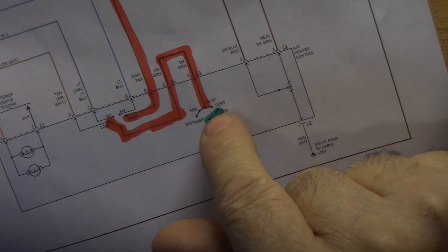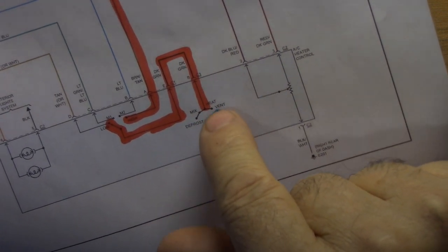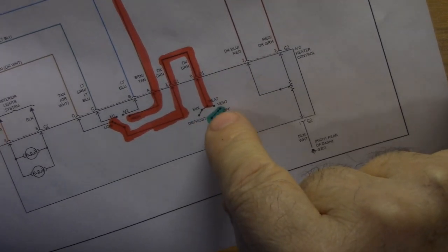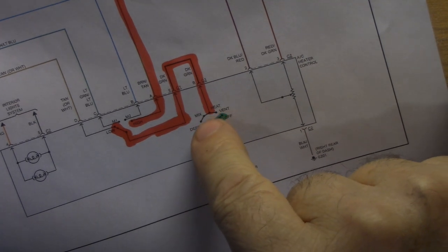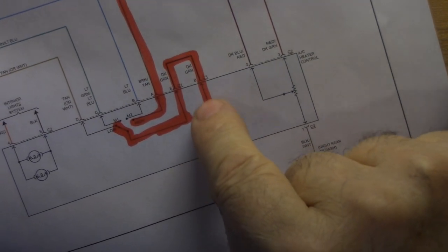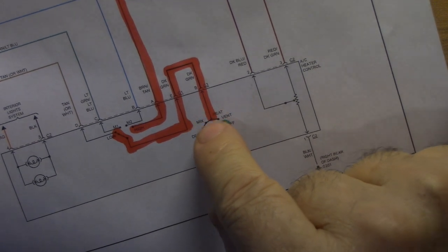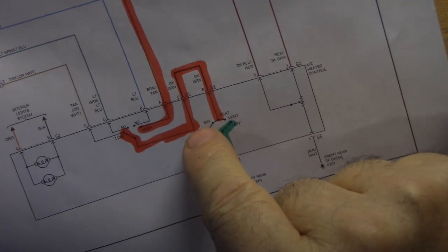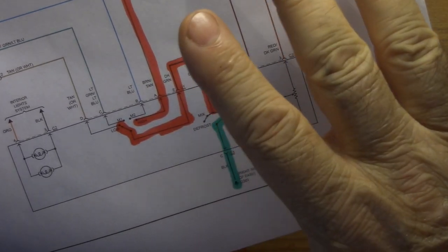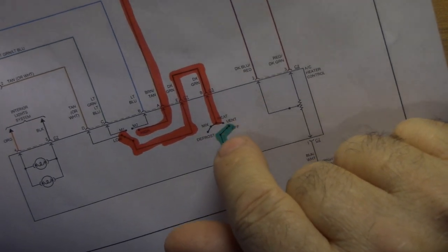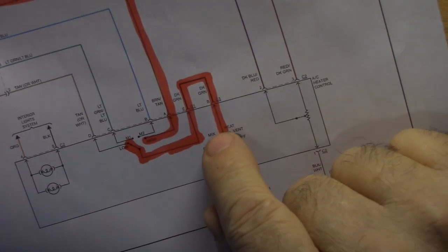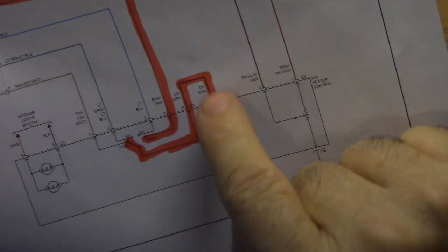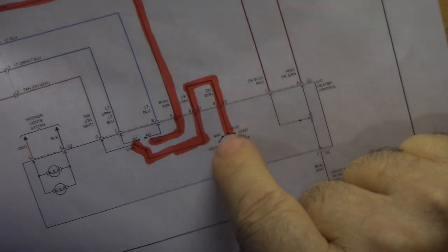The only other thing you have to worry about is the actual on-off switch itself right here. When you have this in either vent, heat, mix, or defrost, as you can see right here, it shows you that the power is always connected. This has nothing to do with the speed, but the power is always connected. This switch controls other things like blend doors, and we're not worried about any of that. We're just worried about the power. The switch does do other things, but as long as it's on in either mode, vent, heat, mix, or defrost, you're going to have a path to ground as long as the switch is good.